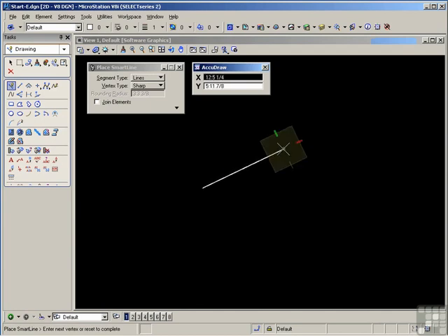But as soon as you data point and the compass moves to the end point of the line, the compass of course aligns with the line, and the x and y axes are not those of the view window or the design. They're simply the x and y axes of that drawing plane indicator. That can be a little confusing because, for example, if I move my cursor vertically, I'm seeing a 0 x value in the AccuDraw window, which is not true for the drawing itself. It's only true for the compass itself. That takes a little getting used to, but you'll see how this works out quite nicely later on.